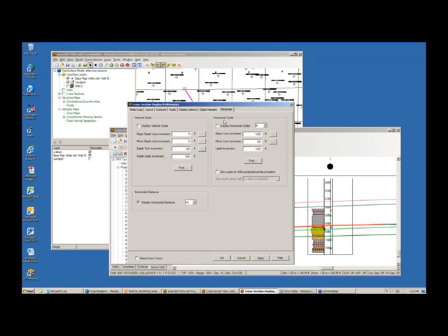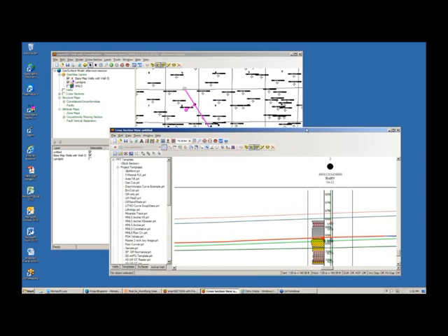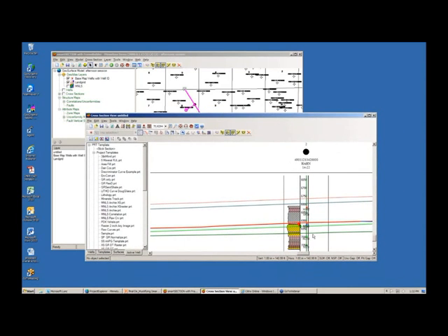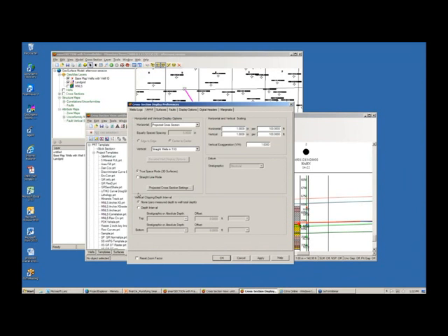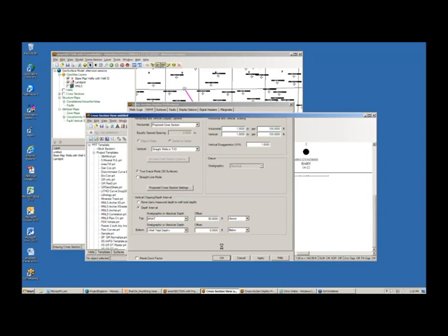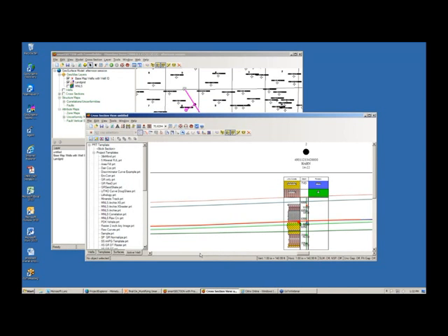So all these display preferences are going to lead us to beautifying our cross sections, and then what we're going to do is actually save the look and feel as a template. I forgot to do one thing. Probably the best thing in Layout is you can come down here and also, just like X section, clip or trim your wells so that the part that you're not really concerned about, you can get rid of, and then you have a much cleaner look to exactly what you're working with and doing.